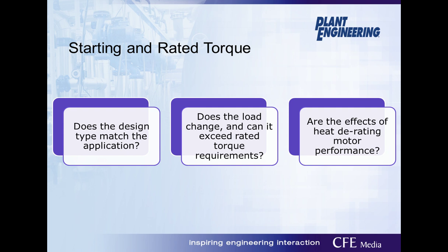So moving on from voltage, the third force acting on the motor that we'll take a look at is torque. Some initial considerations include: does the motor design type match starting and rated torque requirements of the application? Does the load vary over time? Could the load exceed rated torque requirements? And finally, are the effects of heat derating motor performance?